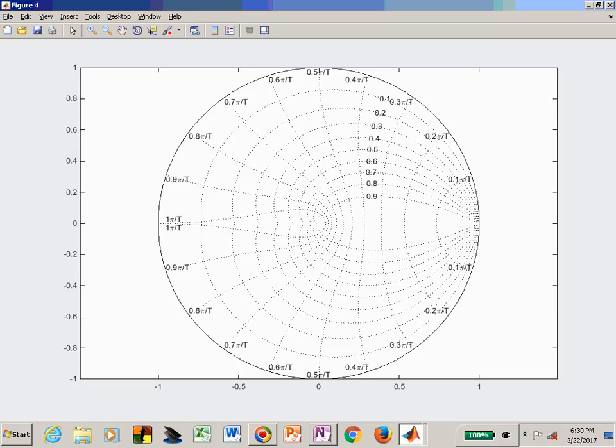And now it looks a little bit better in terms of the angular or right angle representation. Now, you may still argue that that's not a very attractive heart. That's okay. But they're logarithmic spirals, and it's labeled. Now you can see where the 0.9 logarithmic spiral is and the 0.8. Or for zeta of 0.7, which would give you a percent overshoot of 5%, you now know where that lives on this particular line.